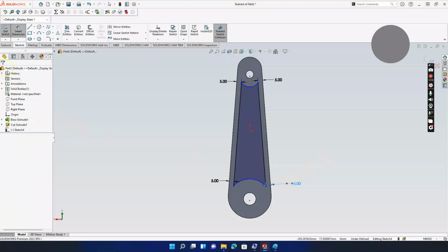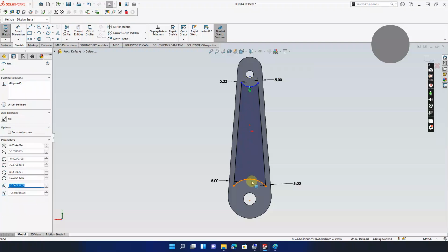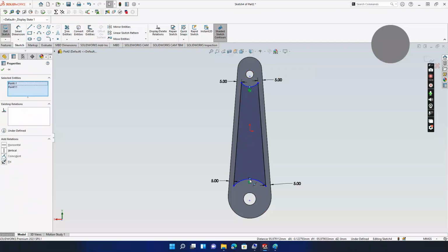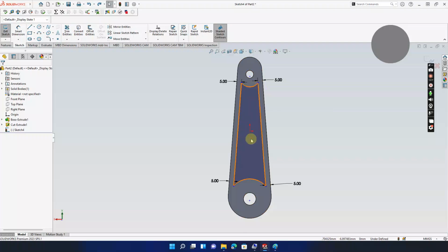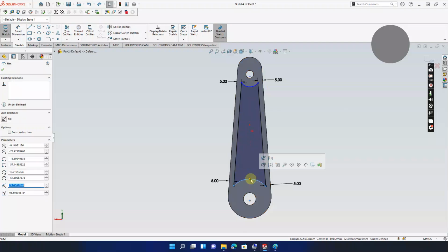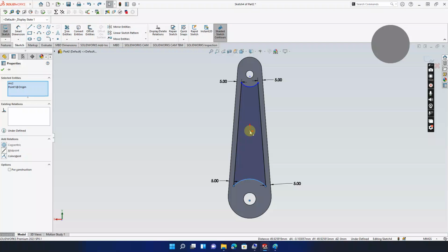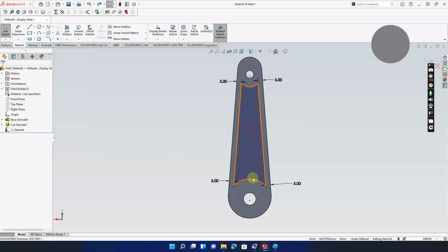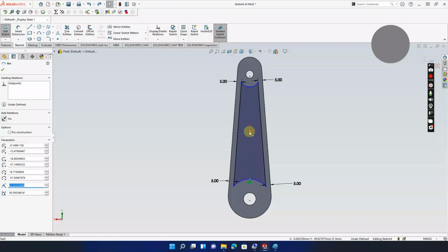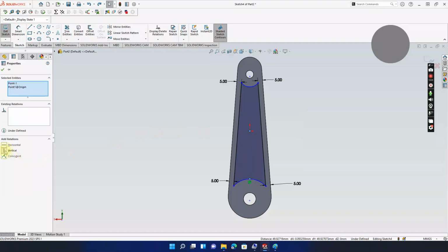Okay. With all that being said, what else are we going to be needing? Now we have to create a relationship between everything. This and the center for this, the relationship should be vertical. Oh, sorry. There was an error there already. So, okay, this and the origin should have a vertical relationship. Okay. The center right here, and this should have a vertical relationship.